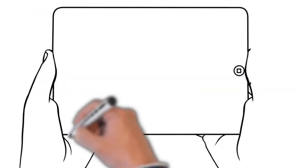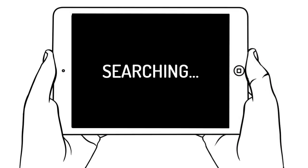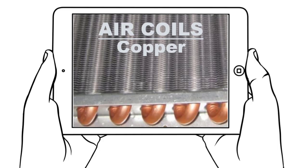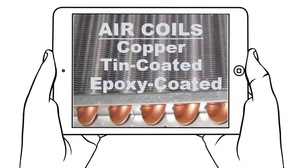The air coils are available in 3 styles, all of which are typical fin and tube construction. Copper. No protective coating is applied. It's the lowest cost, but with the most corrosion potential. Be aware of any environments where fumes or harsh cleaners may be present. Paper mills, petrochemical plants, or hospital retirement communities are great examples of this. Tin coated. This is used typically with the water side economizer only. And finally, epoxy coated for extreme corrosion resistance.